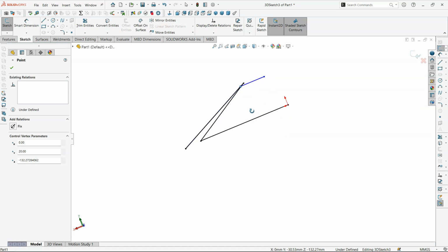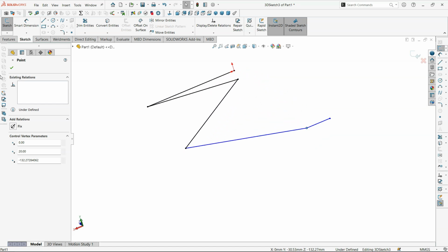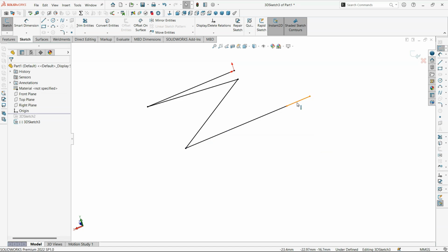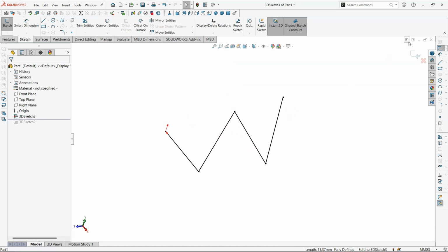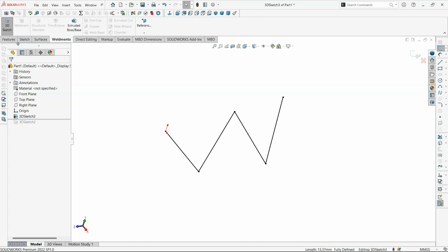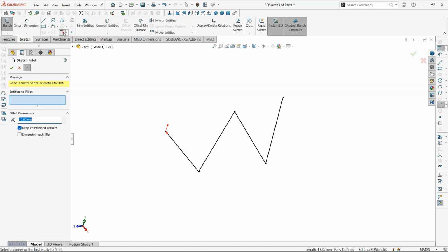and we have y 20 from the origin. So you can see that it is now collinear, and I will make z, let's say 100, because z is basically from this origin. From this origin to this point, the distance of z is 100. So I will click on this to see that it is now fixed. I will just remove this line. Now we have a structure like this here.